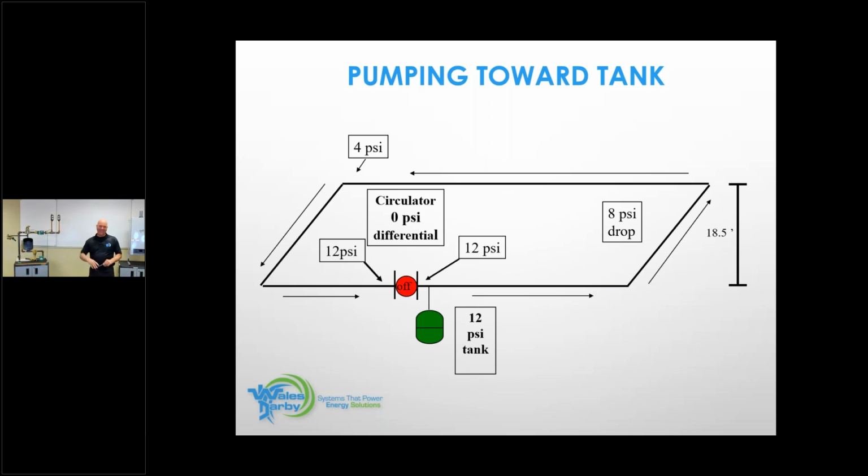Well, one comment was if the tank is in the wrong position, going back to whether it's straight up or sideways, that you could trap air inside the tank and lead to corrosion. Yeah, theoretically you could. This is the method the manufacturer wants, because here's our air elimination. But we see them in all different positions, and I'm not saying it's right or wrong. Definitely corrosion can happen. Oxygen corrosion happens in hydraulic separators, right? With the square, and you don't have an air can on top, and you rot them out. So it can definitely happen. I just get nervous when I see them sideways and they're not supported.